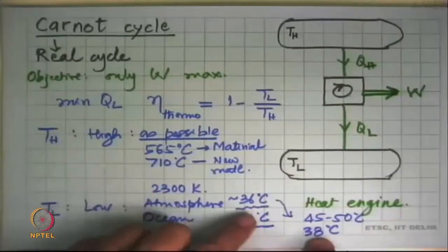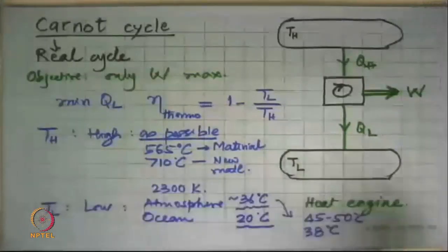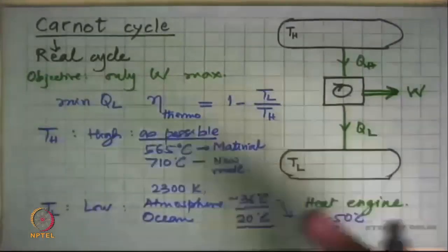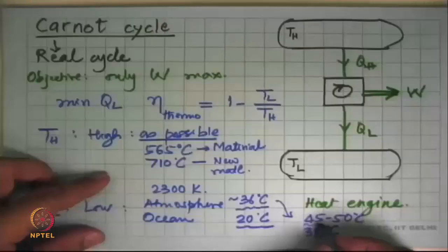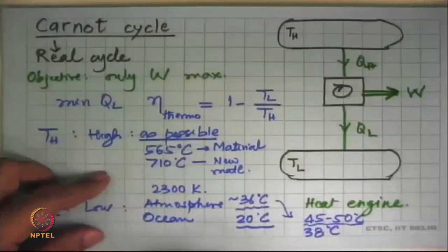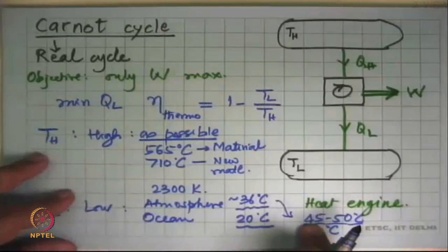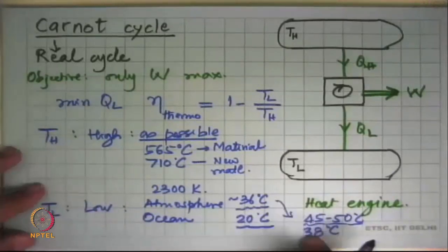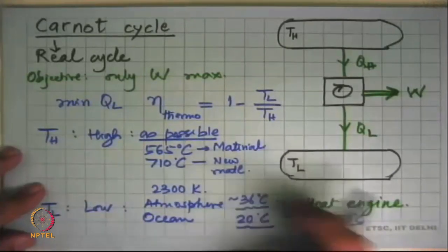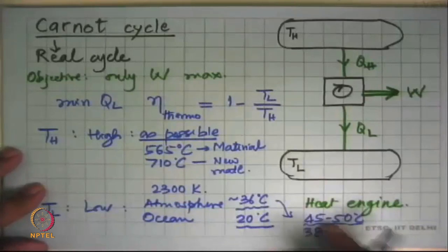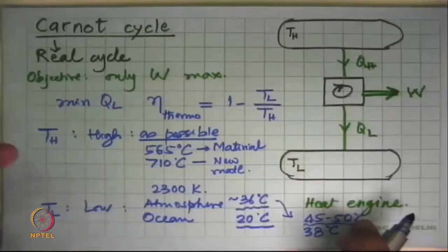Well, yes, 2 degrees difference is there, but then the size of the equipment will become very, very large, and that, in an engineering sense, is not feasible. So that is what people live with, a temperature differential of like 10 degrees, 12 degrees, 15 degrees Celsius, or maybe even 8 degrees, but not 2 degrees. So we brought it down as far as possible and said, look, I can't cool it any further, might as well waste this energy and let it go.